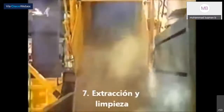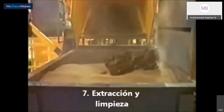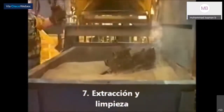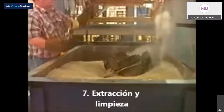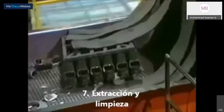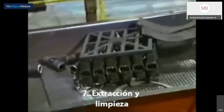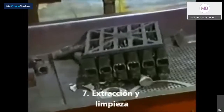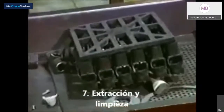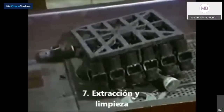After the poured cluster is allowed to solidify, the flask can be simply tipped over. The unbonded sand flows out. No additional violent shakeout or core removal are necessary. Because the foam pattern is left in the mold, no parting line is needed. This allows orientation of the casting to be more flexible and permits clustering, which produces more parts in a given mold area. More parts per mold means higher production at slower molds per hour rates.